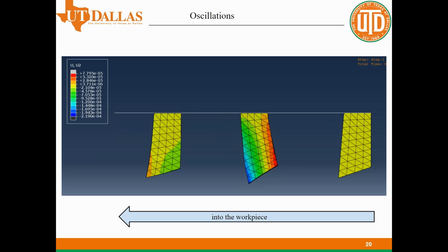We can explain this behavior by thinking of the tool like a spring. It initially starts against the workpiece, and as the top of the tool moves forward, the bottom of the tool is pressed against the aluminum, blocking the tool's path. Before the aluminum yields, the tool ends up stretching back slightly, and once the aluminum fails, the tool tip is released and immediately springs forward. With the tool stretched back, the cutting edge is lower than it started. Once it snaps forward, that cutting edge is higher.